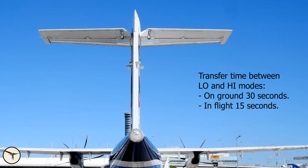And this is the full movement at high speed. As you can see, it's very small. If the TLU is in high speed mode at landing and you are not aware of it, you will have the impression that the rudder cannot be moved. Therefore, checking the TLU is part of the before landing checklist.